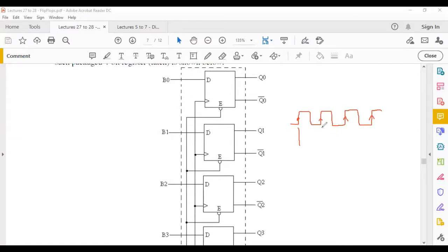That's fine. So for one whole clock cycle, from this one to this one, depending on the frequency of a clock, over this whole time your B node can change state, but your Q node will not change state. It's going to store the state that you had on B node. B node could be a signal which is fluctuating based on the process, but whatever state you had at the rising edge of your clock will be maintained at the output for at least one clock.